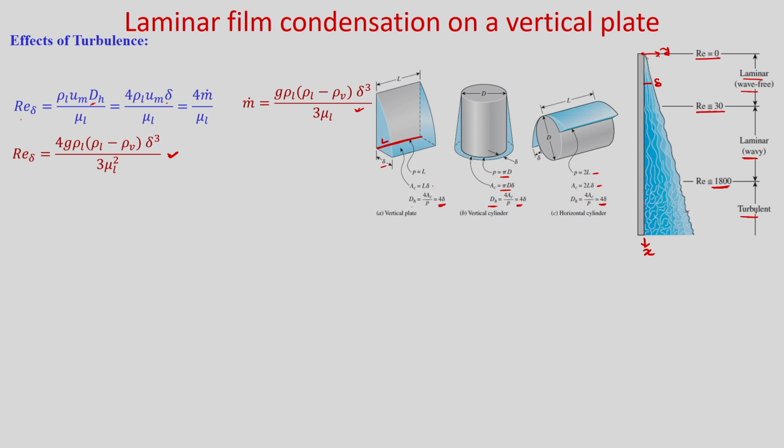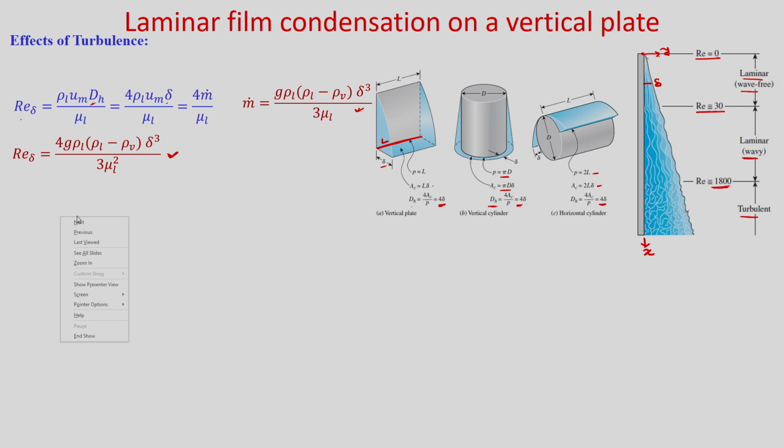Based on this Reynolds number, we will present what the Nusselt number is in the different regimes. The Nusselt number we have already calculated based on the length average. You can write it in this way after rearranging: h bar L times (nu L squared by g) to the power 1 by 3 divided by KL.